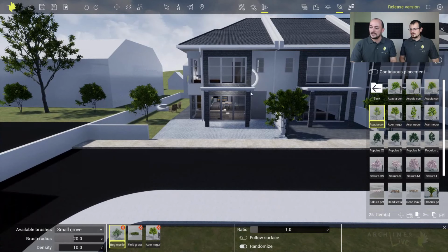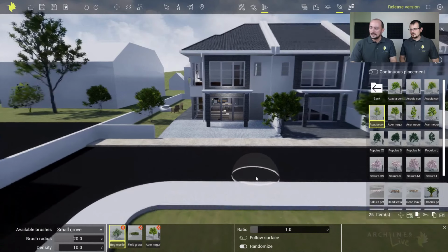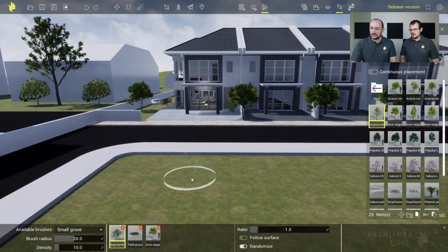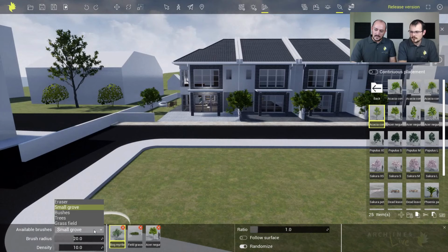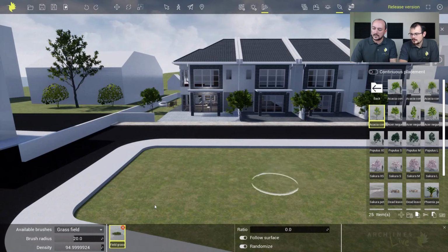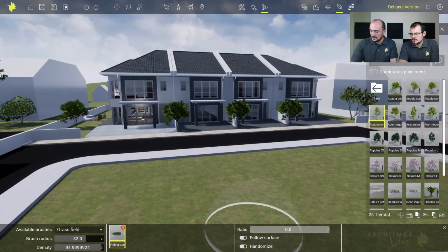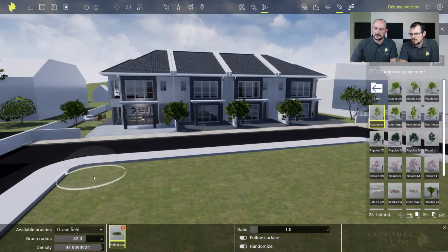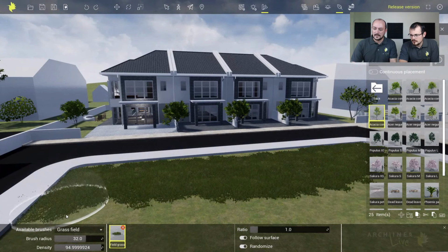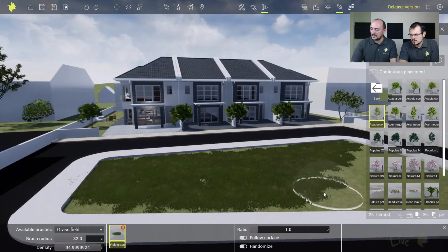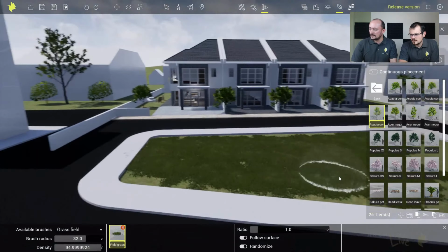Now the foliage painter, as you can see, has this nice brush here, and let's just start first here. We will populate this area first. And this actually comes with a little tray at the bottom with possibilities, with an eraser, which we will use later. Let's just start turning this into a grass field, changing its radius to be a little bit larger, and then just paint this area. I have this dialed down, so I have something like that, and let's just populate this area. See, this is like a paintbrush, literally. I just keep holding my left mouse button and I'm really painting this area